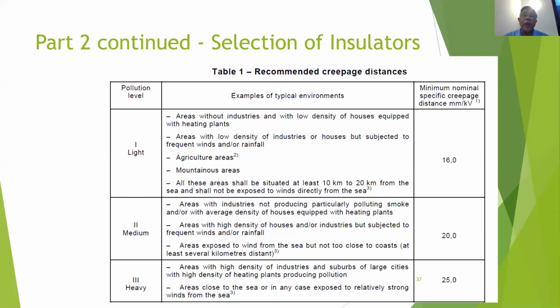Anyway, for light pollution, they recommend 16 millimeter per kV as the specific creepage distance.